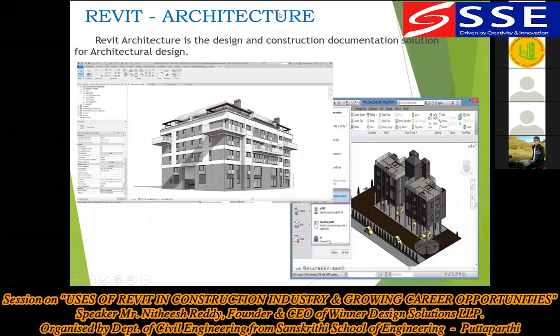Instead of Revit, what if you use ETABS, sir? ETABS is not for everything. ETABS does not have all these features and advantages. You cannot do any fabrication works in ETABS. You cannot do any cladding works. ETABS will not carry any of the construction details or drawings. It is just the structural model you develop, you apply the loads, and you get the final output. The general purpose of ETABS is just to get the detailed drawings. Like STAAD.Pro, it will stop with design. Detailing will not be to the extent you get in Revit. Understood?